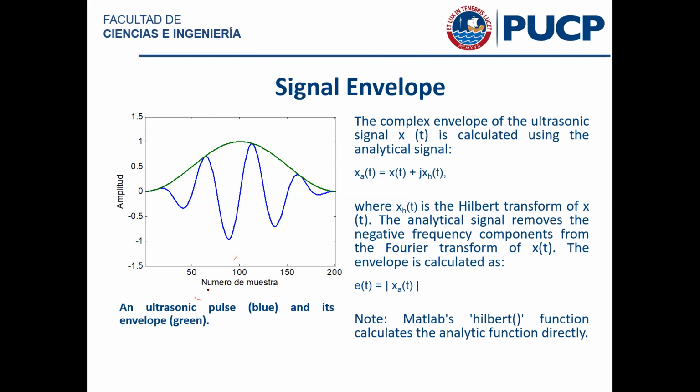If we were to display the amplitude of the actual measured signal, which is the blue signal, you would see that we have portions of the signal that have very high amplitudes and portions that have very low amplitudes, like the points at 0, for example, here and here and here and so on. So if I were to directly create an image of the amplitude of this, I would have very bright spots, which are the high amplitudes, and then very low amplitude spots, where you will have blacks in your image.